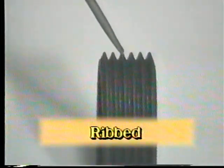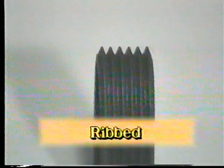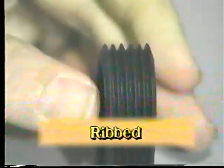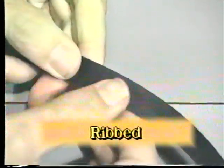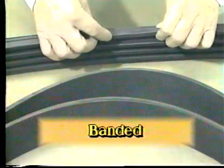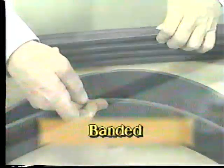Ribbed V-belts have a true V shape rather than the flat bottom design of the conventional V-belt. They have added strength because they need about 20% more tension than a regular V-belt. They also require special ribbed sheaves, which must be more carefully aligned than conventional sheaves. Banded V-belts are really 2 or more belts joined by a layer of rubber and fabric. This connecting layer helps to stabilize the belts and to keep them working as a set.